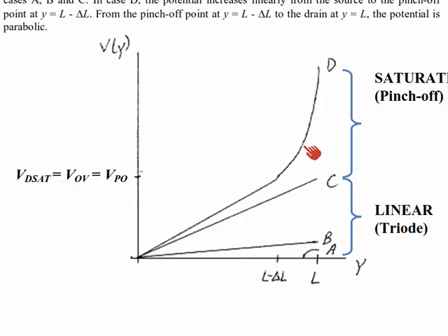And I think you'll figure out right away that one strategy that people employed back then, and some folks still use the same strategy today, even in integrated circuits, but also in high-power devices, is to reduce the doping at the drain end of the channel to reduce the peak electric field there. But we'll not worry about that right now.